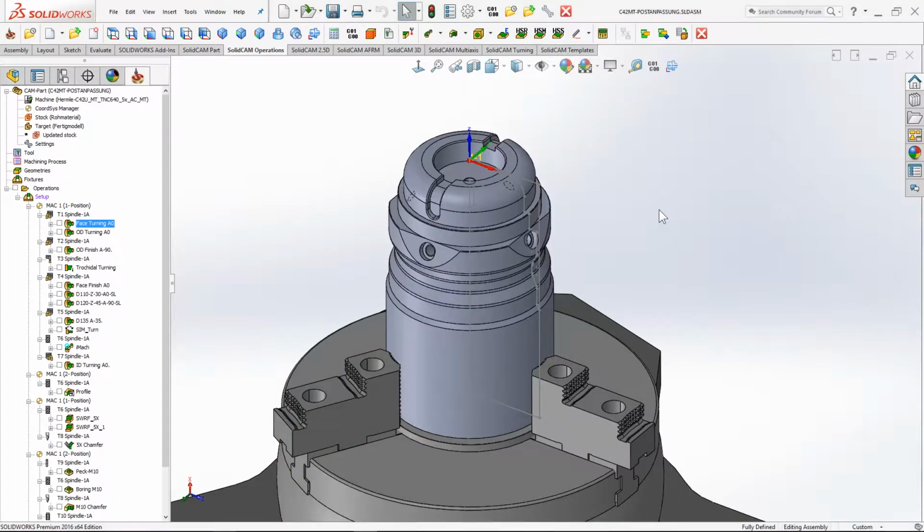Now what I have over here is a small demonstration part which is clamped in the jaws of the chuck, and has the basic geometries where we can show this feature. Now you may ask yourself, why would the 5-axis machine have turning capabilities? Well, there are some geometries on the parts which are cylindrical, which require higher precision, and the only way to do it is with a turn. So for example, this radius over here, maybe an internal diameter, etc.